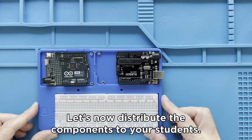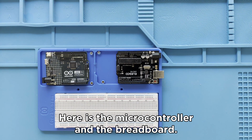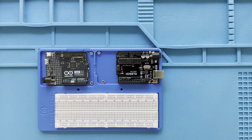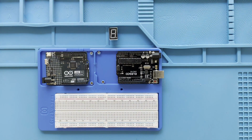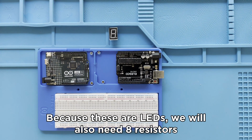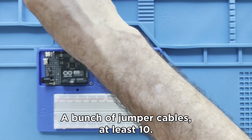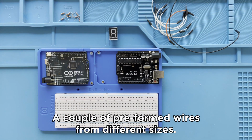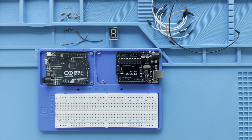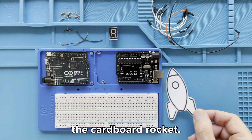Let's now distribute the components to your students. Here is the microcontroller and the breadboard, the 7-segment single-digit display. Because these are LEDs, we will also need 8 resistors of 220 ohm, a bunch of jumper cables, at least 10, a couple of preformed wires from different sizes, and let us not forget the most important part, the cardboard rocket.